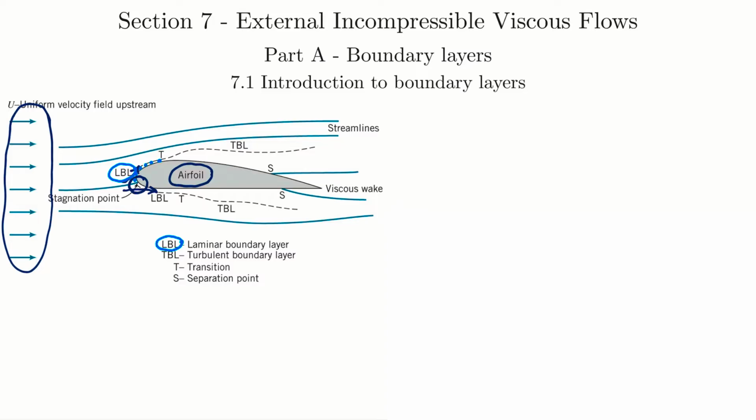What they're trying to show here with the dashed line is the edge of the boundary layer. We can see it growing, the same way we remember with pipes. That will grow as you move along the surface, because those frictional viscous effects influence a larger and larger proportion of the flow as you move along the surface. Then T is showing the transition point, because boundary layers start off as laminar and then transition to turbulent as you move along surfaces. And at the transition point, what they're demonstrating, again with this dashed line, is that you can see it actually takes a bit of a jump there.